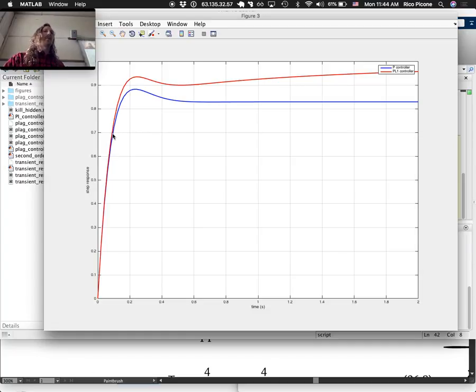If we increase the gain, we're going to shorten the rise time too, which we don't have any reason to think is bad for this system, so we're probably okay with doing that. We don't even go far enough out here. Even in 2 seconds, we don't see the steady state value that we come to. So we can't quite evaluate that performance yet. But my guess from just eyeballing this is that we're not getting a factor of 10 better than the original steady state error, which is like, what would you call that, 17%, 18%?